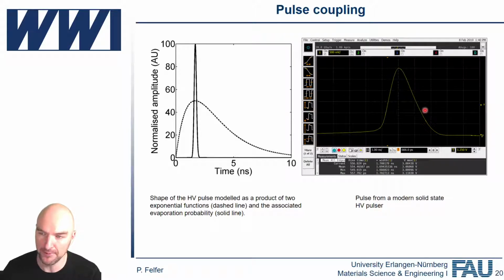And if your sample doesn't have enough conductivity, we're going to have some effects because it's kind of like having a little capacitor, and it will get resonances. And these resonances will just break your sample. So you might get a couple of atoms coming out, but it will blow up pretty soon. If you put silicon dioxide into your voltage atom probe, you're going to get a couple of atoms, and then it will just blow up.